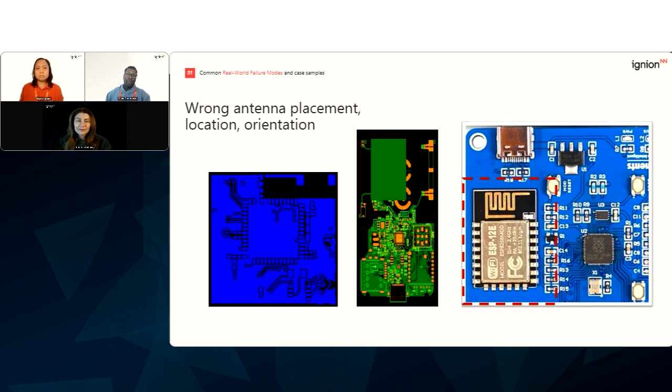And if you look at the middle board, again, there's a footprint for the antenna, sitting on the top right. And you've got some sort of transmission line going down to some ground plane. And obviously, the ground plane is not sufficient for starters for this sort of application. This was actually a cellular application. And also the location of the antenna is incorrect. In fact, you want to mount that antenna at the top of the ground along the width of the antenna. And preferably, you have most of the ground plane with copper fill, for proper RF performance, right?